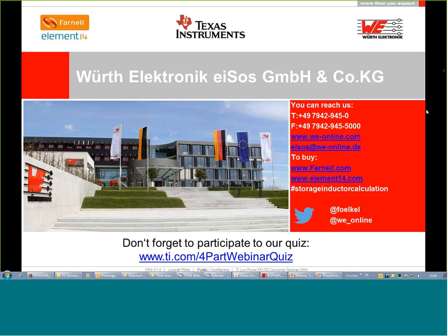So I would say a good switching frequency today is between 500 kilohertz and a maximum of 1–2 megahertz. Very rarely, if you have really high current, you will use 3 or 5 megahertz. You can get chips from Texas Instruments without any problem that switch at 8 to 10 megahertz. But it's always a balance. If you turn the frequency knob too high and the inductor becomes small, you will see that in other places you will need other inductors, other capacitors, other components that affect the performance.